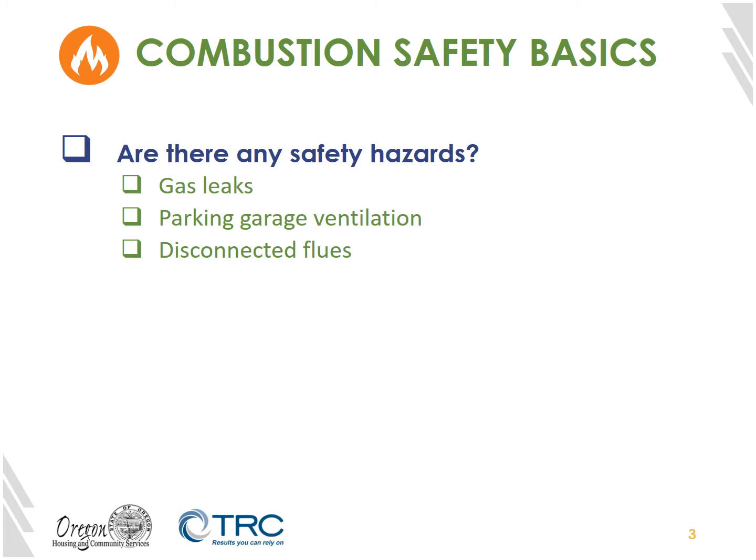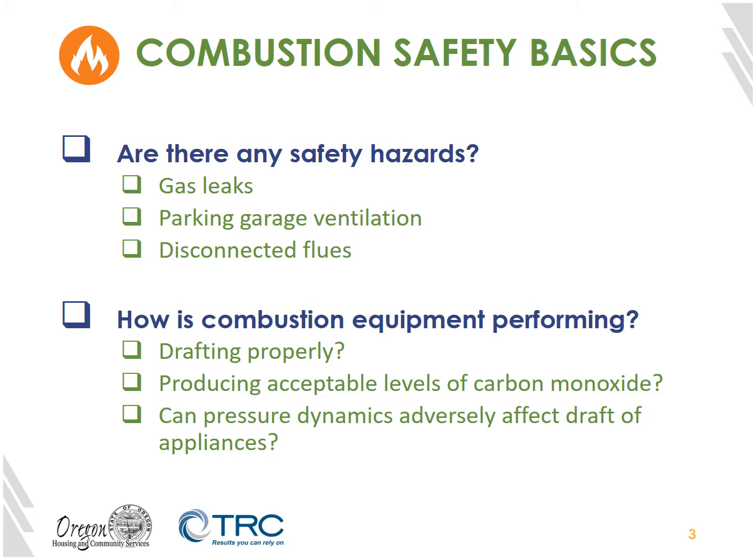So some basics of combustion safety. First, we want to ask ourselves, are there any safety hazards? These could include things like gas leaks, parking garage ventilation, making sure that it's functioning properly, or potentially disconnected flues. Next, how is the combustion equipment performing? Is it drafting properly? Is it producing acceptable levels of carbon monoxide? Notice that's not zero carbon monoxide, but acceptable amounts. Or could pressure dynamics adversely affect the draft of our appliances?